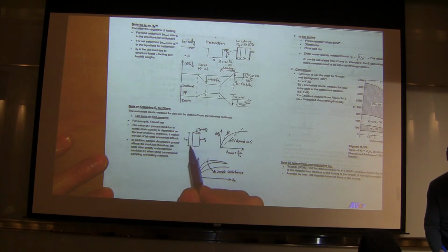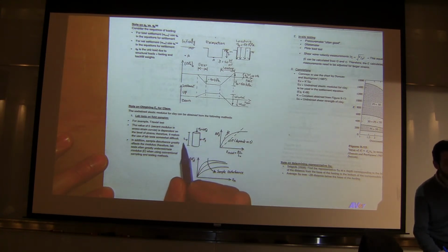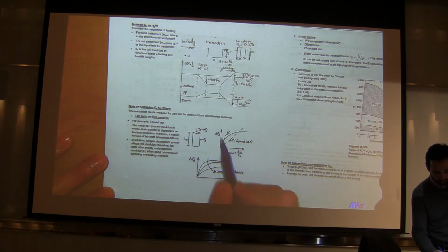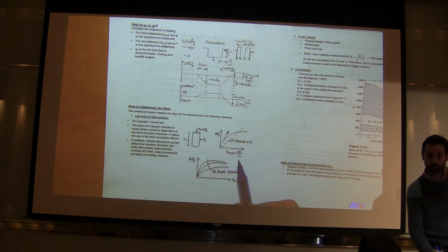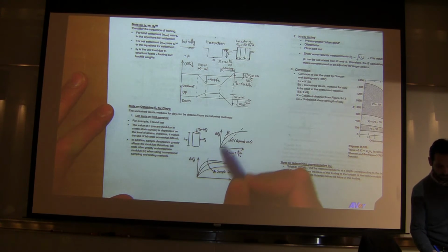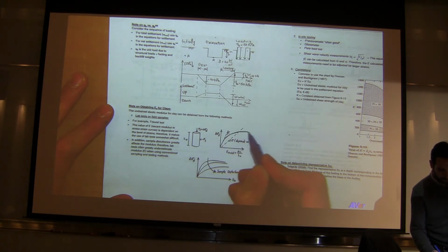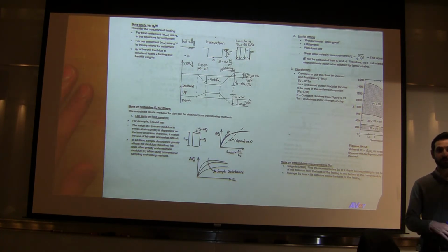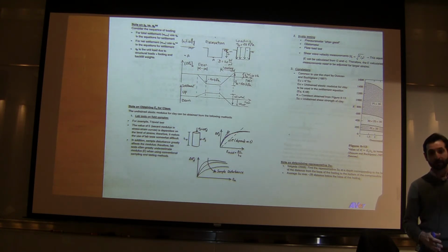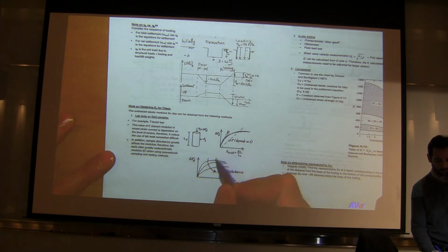The length of the sample in the triaxial test is L naught, that's the initial length, and then if you plot delta sigma d versus axial strain, where axial strain is defined as delta L divided by the original length, you get a curve that looks like this. Now, the slope of this line gives you the elastic modulus, just like how we said it in sand. Now, in sand, we had one problem, that the slope of this line was dependent on sigma 3, so it was stress dependent. This is now clay, so we have less complexity to deal with because it's not a stress dependent problem. But we have to figure out something to do with the non-linearity of this curve.